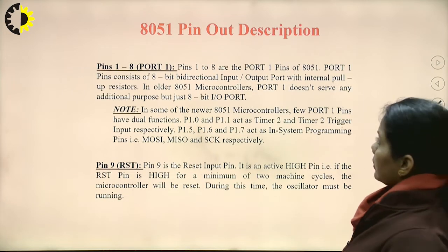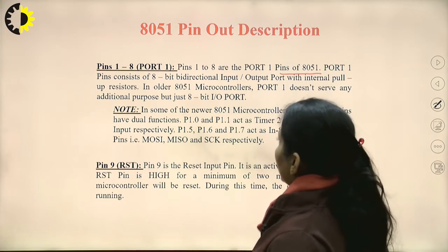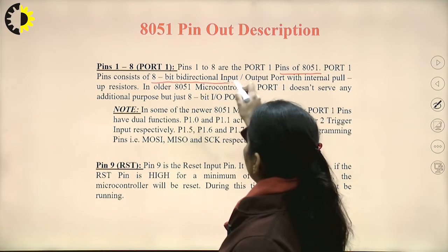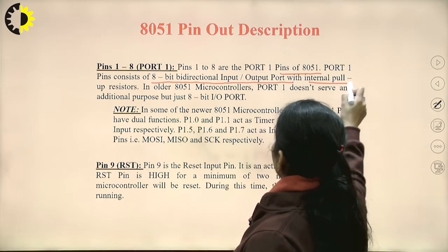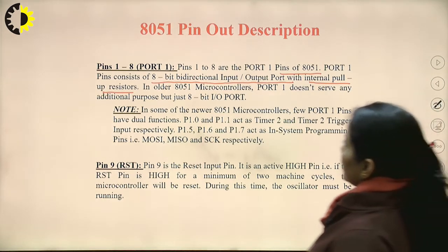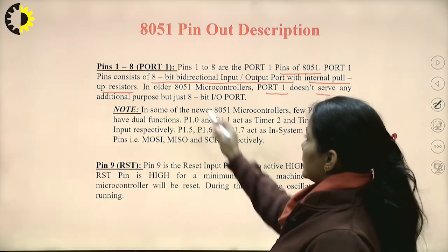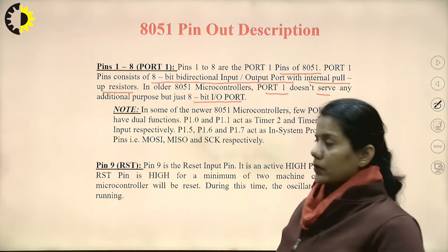Pin number 1 to 8, these are the port 1 pins. It consists of an 8-bit bidirectional input-output port with internal pull-up resistors. In older 8051 controllers, port 1 does not serve any additional purpose but is just an 8-bit input-output port.